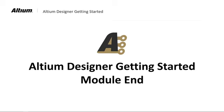This concludes the Starting a Project lecture. In this video, we started a new project, added both a schematic sheet and a PCB to the project. In addition, we also had an overview of the library options available in Altium Designer. In our next module, we will start the schematic capture.